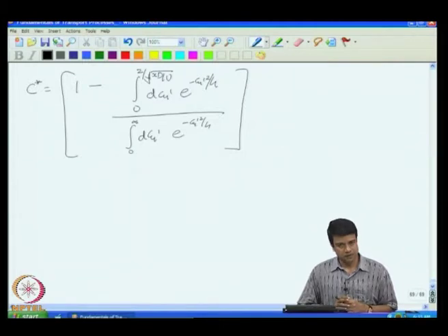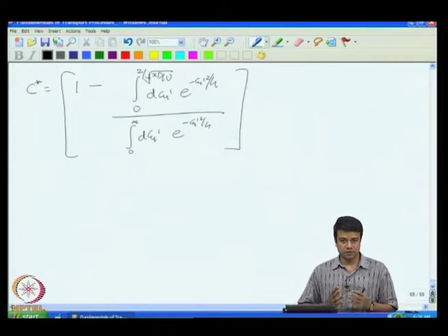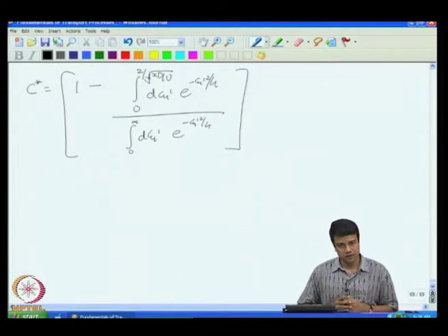Instead of z by square root of dt, I have just substituted z by square root of dx by u. In the previous unsteady problem, z by square root of dt was a dimensional necessity. That was the only dimensionless group that I could get. In this case, it is not a dimensional necessity. I could define other dimensionless groups; z by x is one of them. However, we used the fact that the equations are of identical form in order to write the solution quite simply.